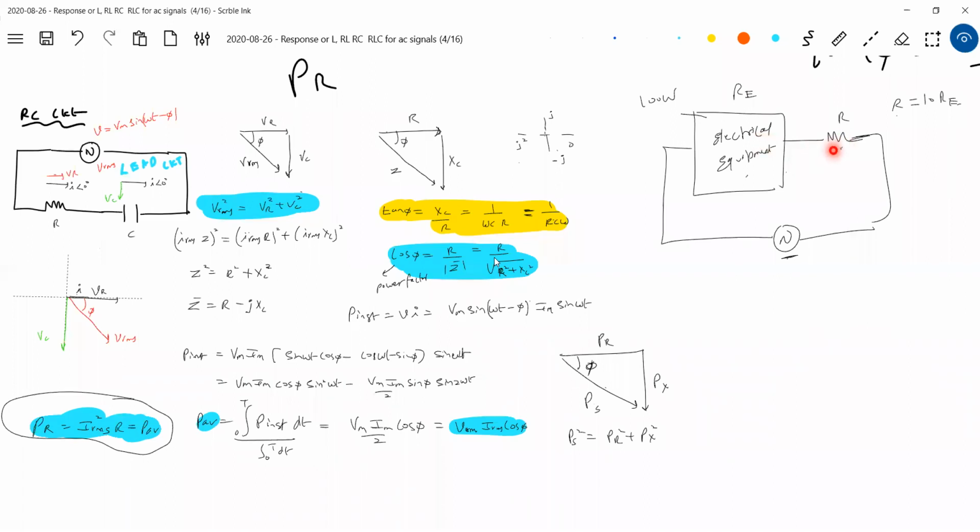Go back to the voltage divider formula here also. Of the applied voltage, the share will be more here than in this particular thing. Therefore, if any voltage increases, first it will increase more here than this one. So first this will burn out, this will get damaged. Okay, fine, I'm protecting the electrical equipment, but look at the bill. 90% of the power I'm wasting here. Only 10% is utilized by the electrical equipment. For every 1000 rupees, 900 is taken by this, only 100 rupees is utilized here. So this is a very bad design.